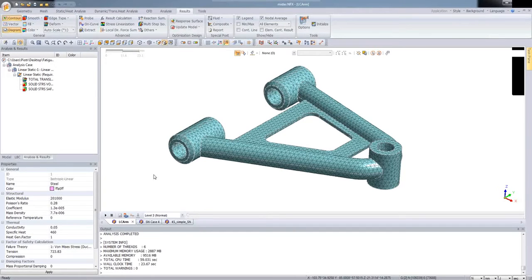The other name of this method is the crack initiation method. So this defines that the failure criterion right now is the life to initiate a crack. We can say that once an engineering crack appears, the failure is said to have occurred.